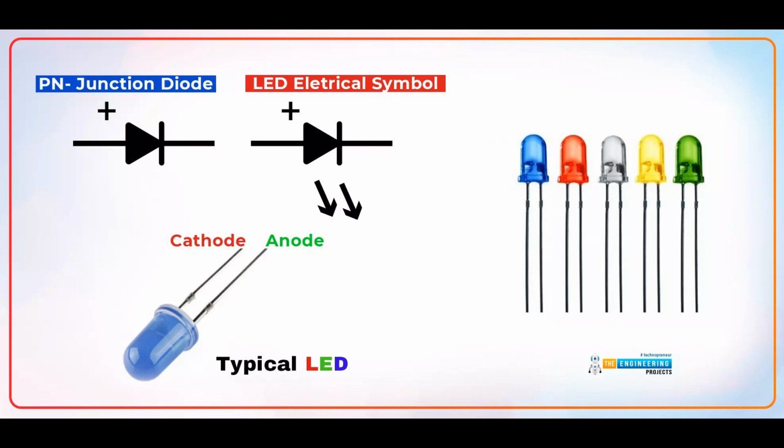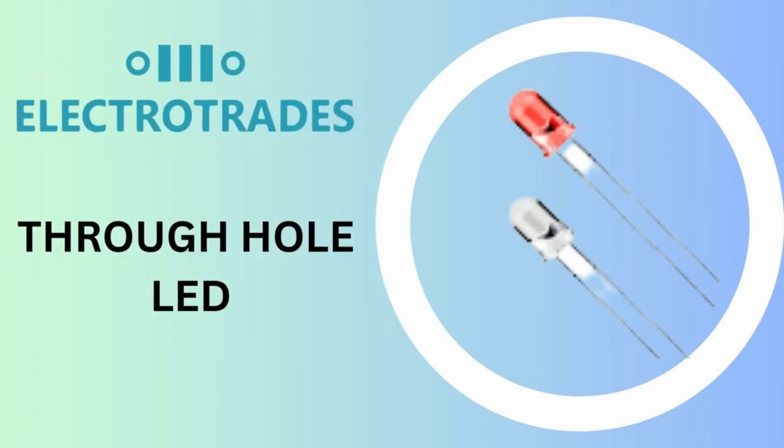Barrier potential. During the formation of the P-N junction, a potential barrier is established across the junction due to the differences in the majority charge carriers in the two regions. The potential barrier prevents further flow of charge carriers across the junction without the application of an external voltage.